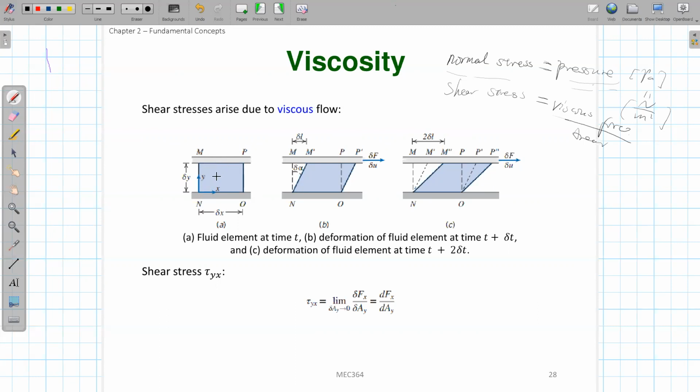Basically, a liquid is defined such that if we have a fluid in the middle of these two plates and I move the top plate, the fluid will keep deforming. The strain angle will keep increasing. We also talked about the non-slip and slip boundary. In this case we have a non-slip boundary, which means that the fluid at the interface has the same velocity as the plate, with no relative velocity between the fluid at this point and the plate. On the bottom, the fluid has the same velocity as the bottom plate, so its velocity will always stay 0. That's why it keeps deforming.